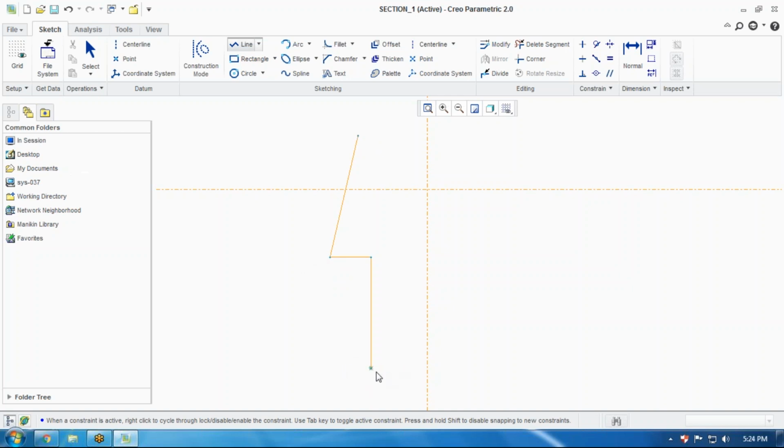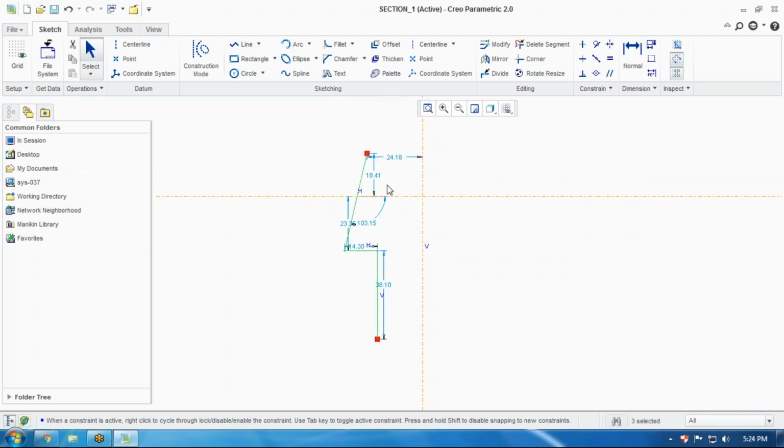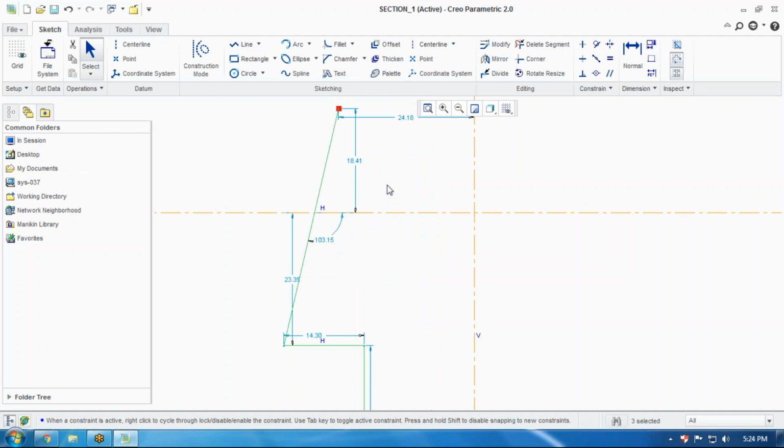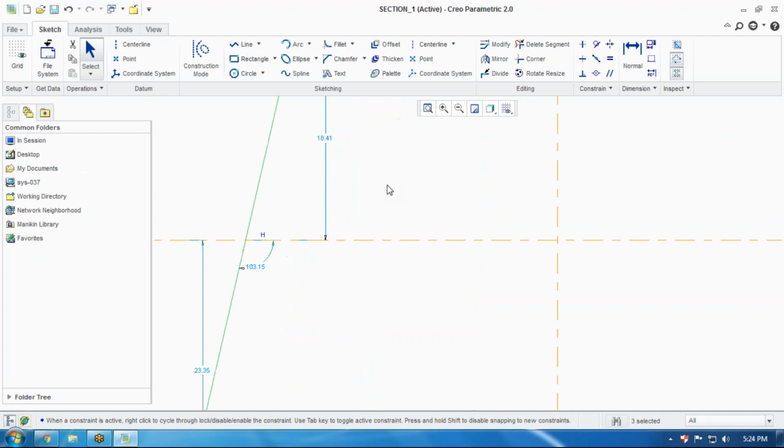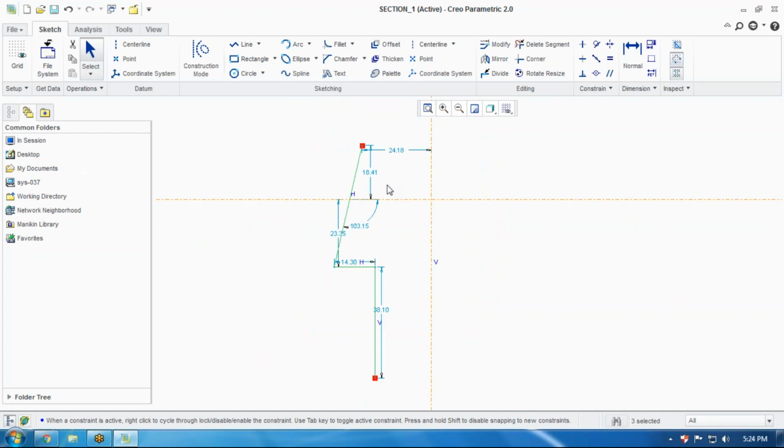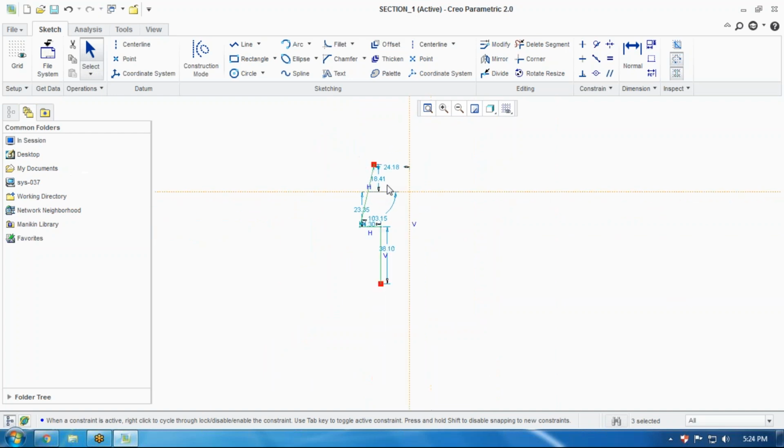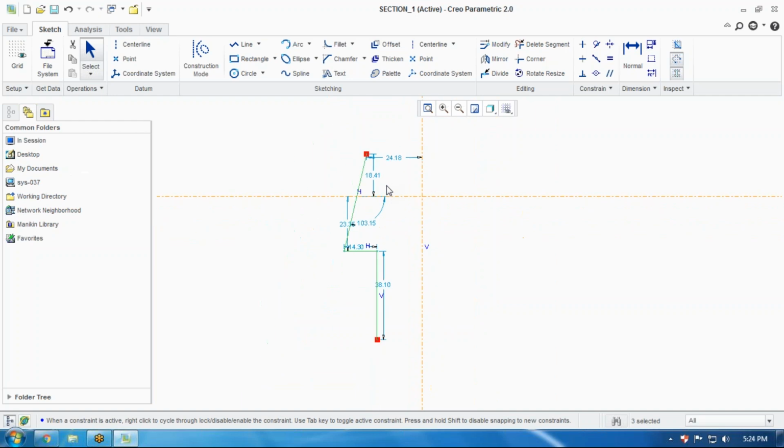Like this. So we can see there, if I'm okay with the features, double click the center ball and you will exit. After creating the entities, if you want to zoom in or zoom out, just go for the scroll mouse button and use it. If we scroll backward, it will zoom in, and if we scroll forward, it will zoom out. Zoom in, then zoom out.